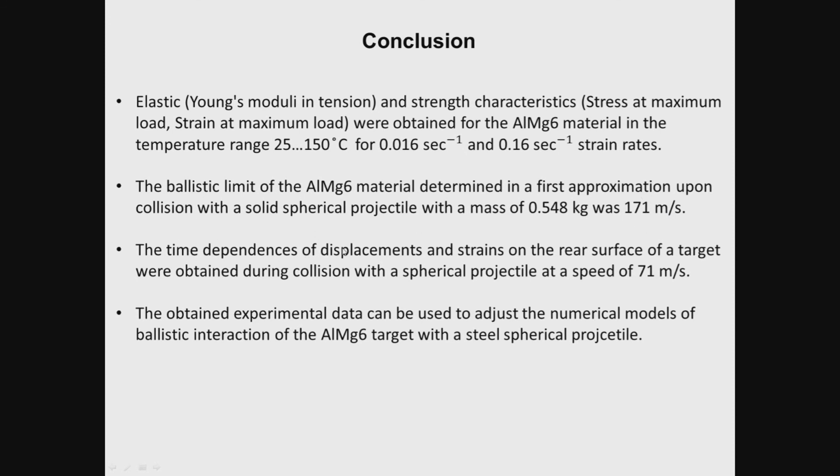So we have the time dependencies of the displacement on the rear surface of the target, and also the time dependencies of the strains. All of these data can be used to adjust the numerical models of the ballistic interaction of the AlMg6 target with the spherical steel projectile.